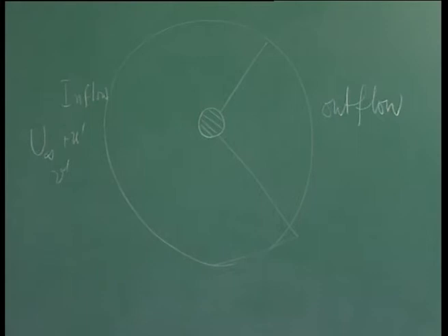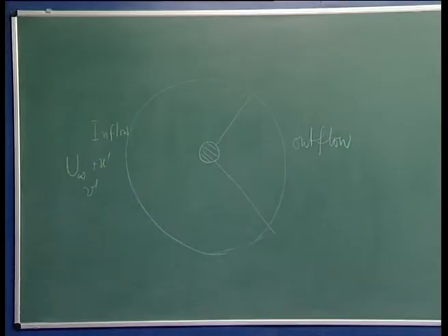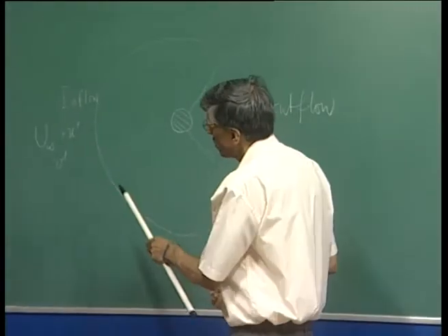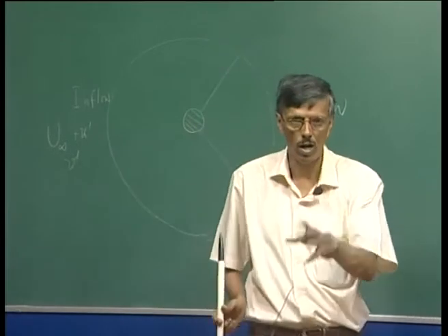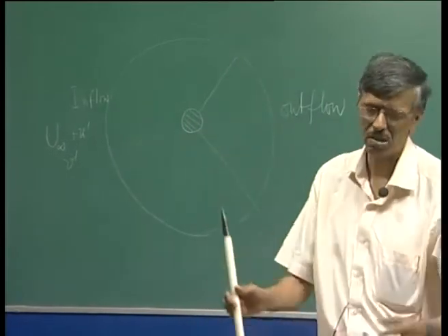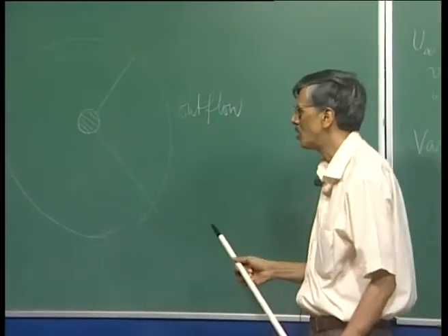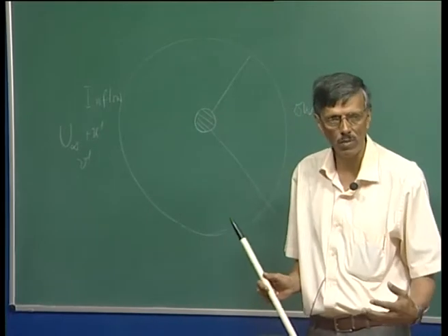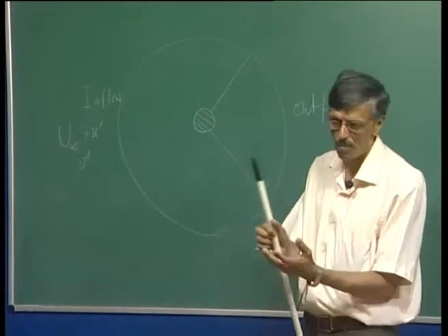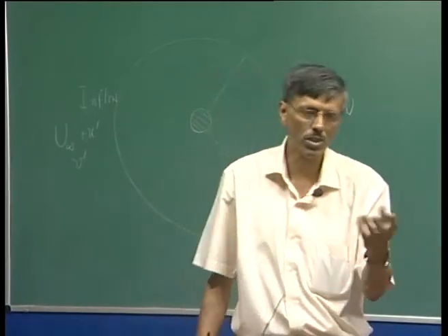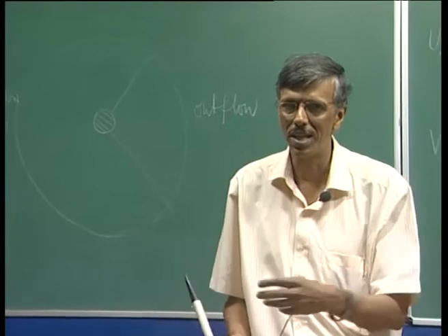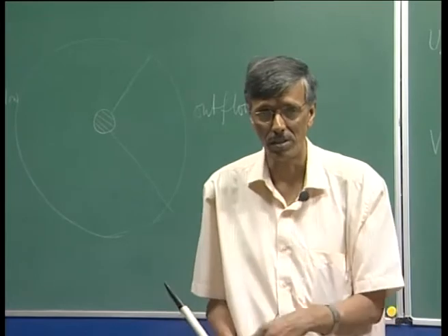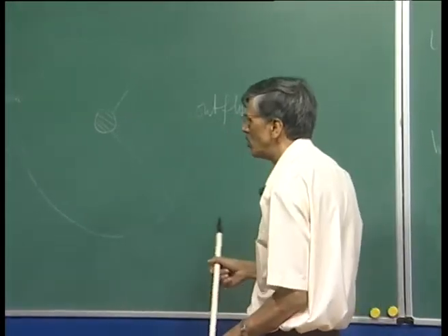Well, if you have done a pretty good tunnel design and the contraction is not too rapid, then it is quite okay to consider that u prime and v prime have the same statistics, a kind of isotropy you can talk about. But if you also want to include some additional information you may have, for example, in a channel flow, v prime is going to be less than u prime, you can put it in there, and you can also get this nice wall normal structure. There are experiments available, so we can do that.